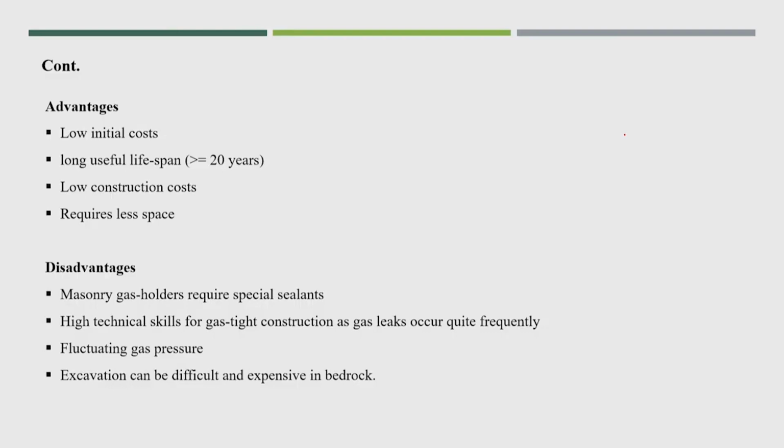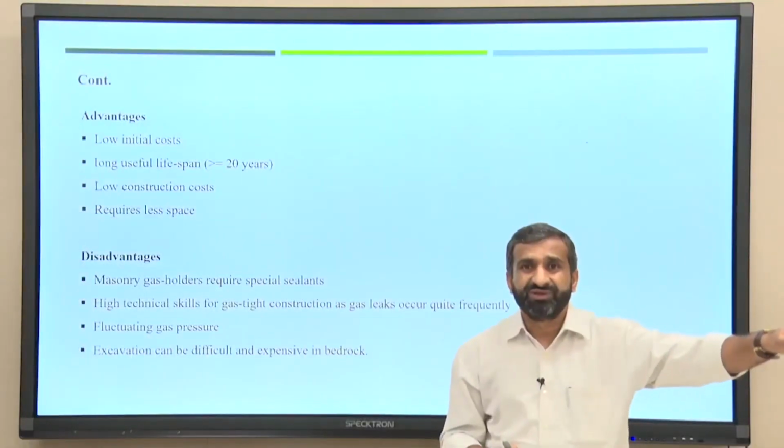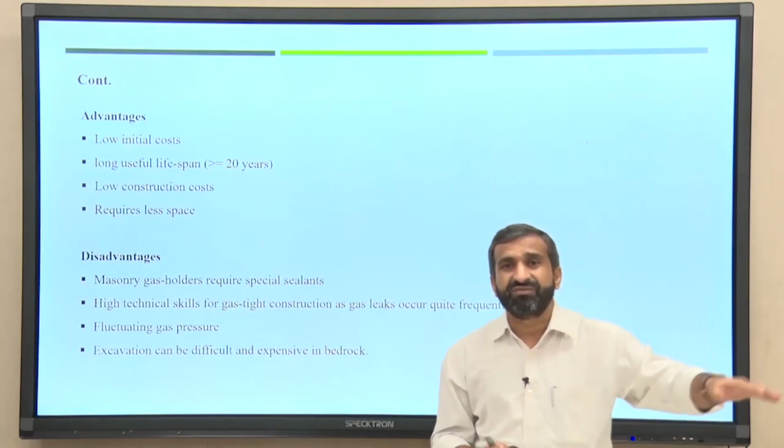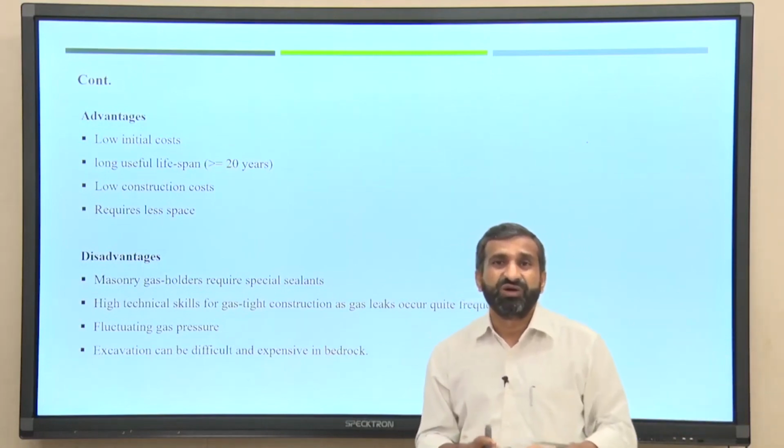I think this gas leakage is mostly because of what I said, that moisture is coming out, and because there will not be any evaporation inside the pipe, the water will accumulate in one particular location, and because of that the flow of gas will be reduced. And because of that a lot of gas, rather than coming to the gas pipe, will come out into the outlet. So, you will see a lot of air bubbles in the outlet tank.